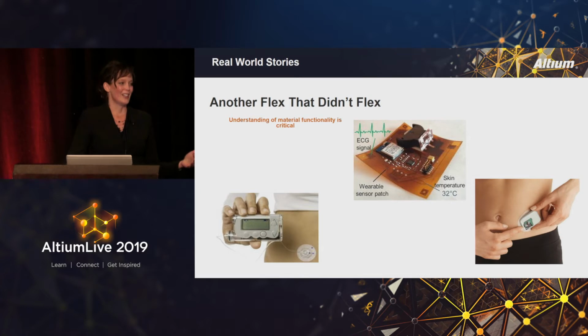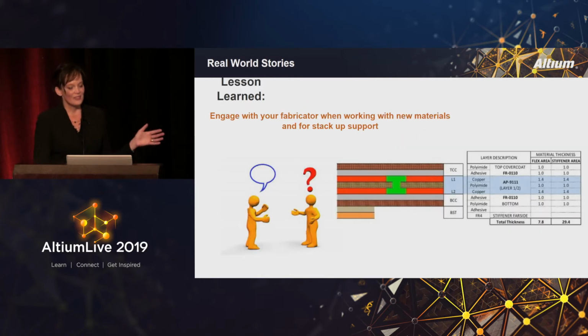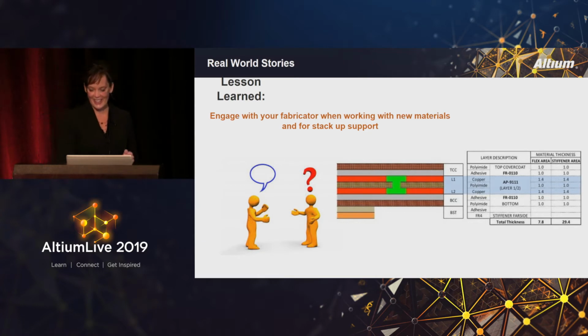Now, overall, I have to say that the supplier that originally started the design wasn't a PCB manufacturer. They were a foundry doing a bunch of other things for this company and just were doing a little bit of circuits on the side. I think if you had sent that design into a board manufacturer or flex manufacturer with rigid material and polyimide cover lay, all the bells and whistles would have went off. I mean, what are you doing? This doesn't make any sense at all. But lesson learned, right? So always work with your fabricator when you're working with new materials.